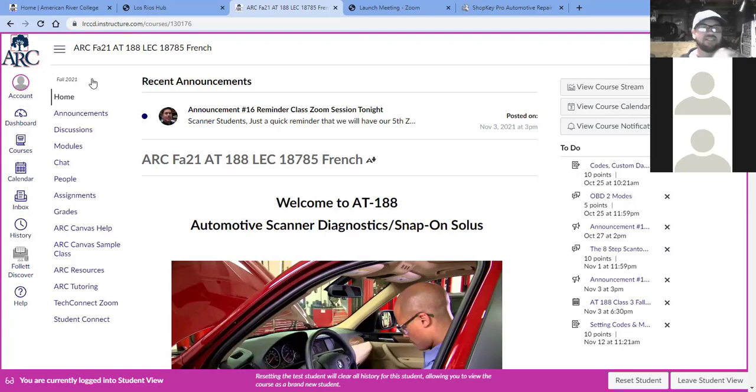I also gave you that great tech tip on using the volumetric efficiency calculator to diagnose defective mass airflow sensors. And so we are going to have some upcoming assignments on that. That's going to ask you guys to go out and do a test drive and do volumetric efficiency calculations on your vehicles. And I'm really excited to see some of your data and what you guys find from that.